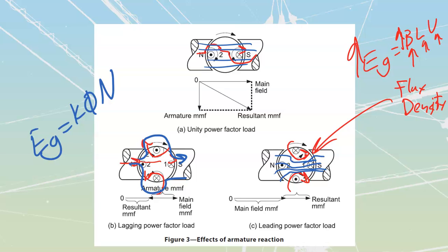And then they say with the lower the power factor. Again, I find this language to be a little bit confusing. Maybe you don't. Maybe it's just me. But I find it easier just to say that with more lagging power factor, the greater the voltage drop, and with more leading power factor, the greater the voltage rise. Technically, they are correct in the way they write it out. It's just a harder thing to visualize like that.